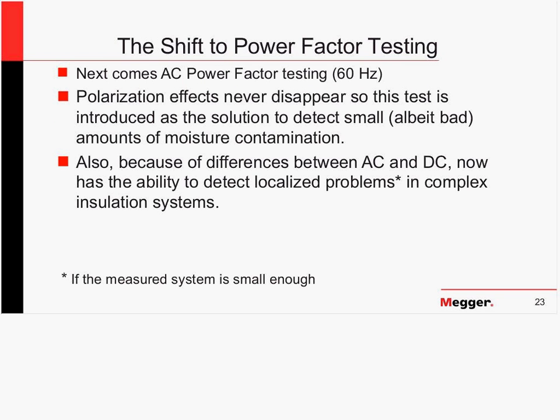So let's talk about this shift to power factor testing, because along comes power factor testing with an AC voltage source at line frequency, and with this, your polarization effects never disappear. You never reach a time when they're resting, because suddenly you're reversing the applied field and the polarization processes start all over again. Because small amounts of water contribute to polarization effects, it was desired that they don't disappear, so that you can detect small amounts of moisture contamination.